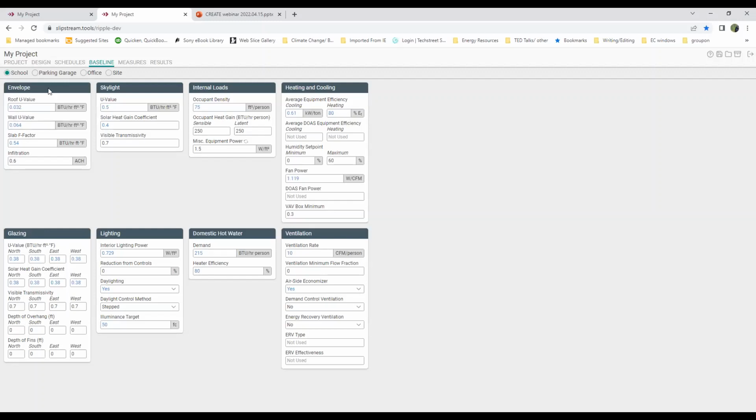Some of the practical things that the students could do would be to walk around the building and see what kind of lighting fixtures there are. Are there parts of the building that have been retrofitted with LEDs? So we have CFLs and T8s or T12s. Then calculating the lighting power density is a really interesting exercise that we teach a lot of our interns when we do field work too.